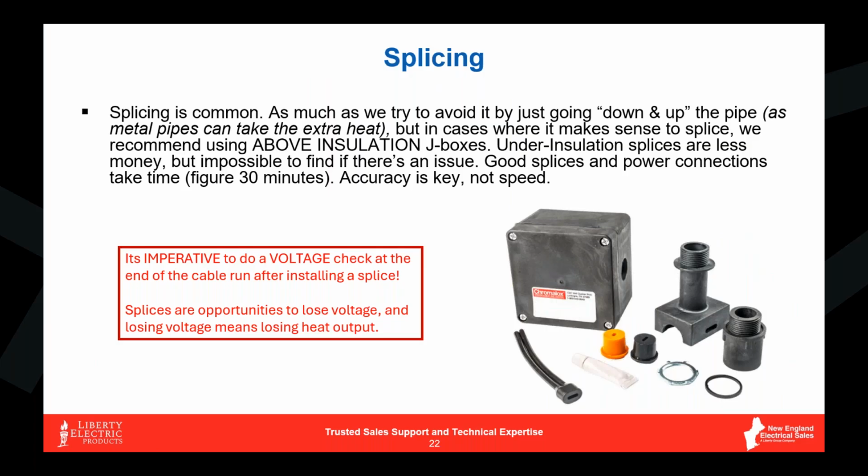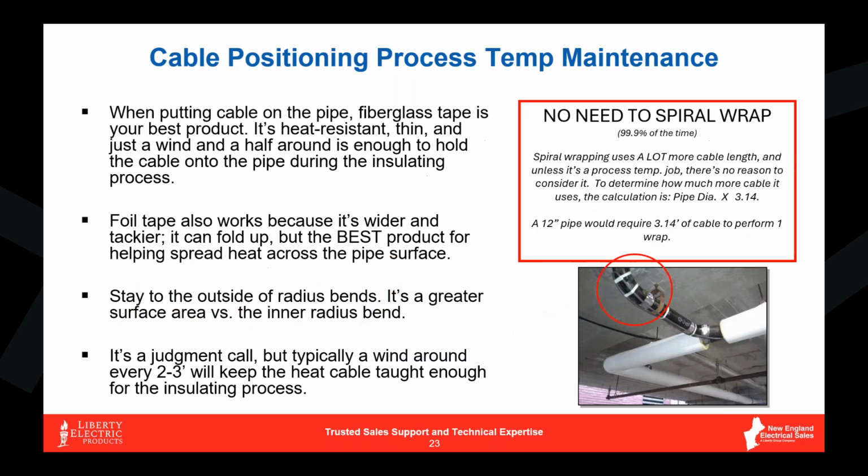And remember that every splice opens up the door to another potential termination issue. So it's very imperative to do voltage checks on your splices. Make sure you're getting the same voltage before and after. And if you do, I would also recommend taking pictures of your terminations, logging those in your job file that you can send off to your PM or to the GC or to the end user. It's just a good CYA policy practice that we'll be touching on a little bit later as well.